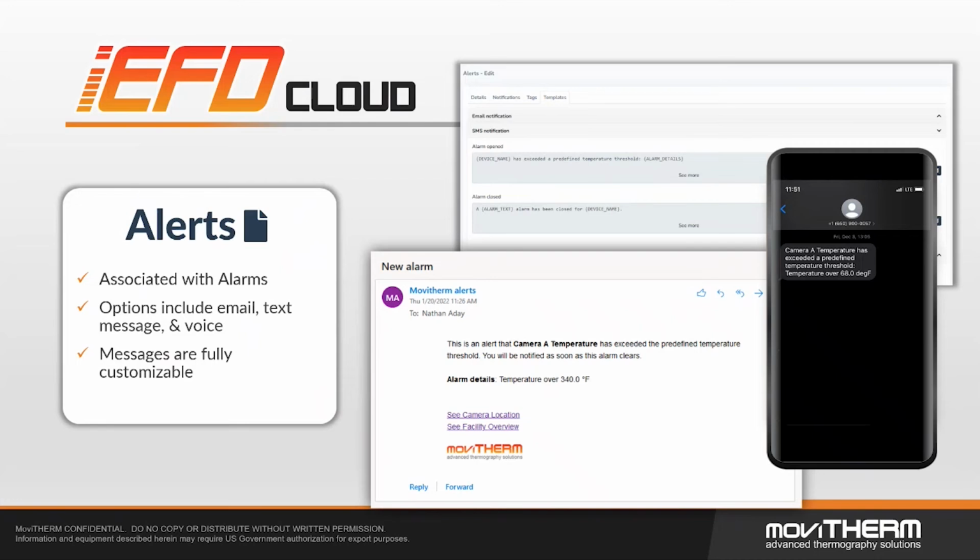And you mentioned earlier that these can be staged or tiered as well on who receives the alerts or the notifications. Exactly. It is by level of severity is what I call it, right? Sometimes you just want to check things out, and you may have set your temperature threshold to something that's rather critical. It's right above the normal, so you don't want to drive people nuts and send out 20 people, big fire alarm, when there may be something there that isn't quite there yet. But it's a level of concern, so you definitely want to check it out, right?